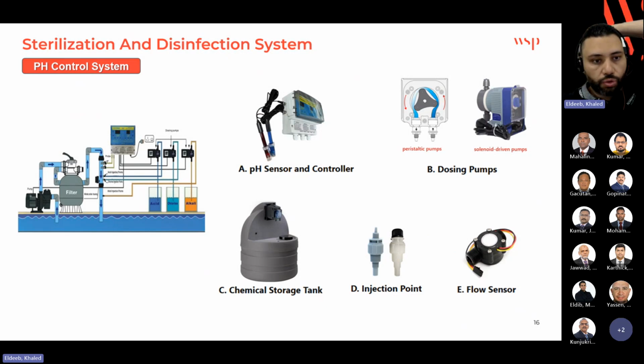Also we need to consider installing safety interlocks like a flow switch to prevent dosing when pumps are off, and overfeed protection in the controller as well.